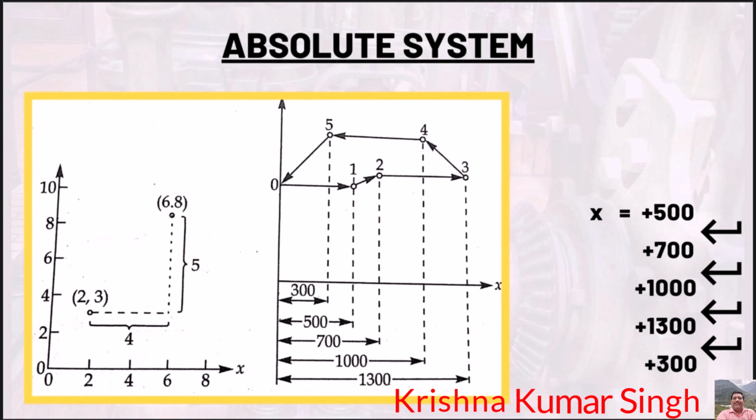Next we have the absolute system. In this system, the movement commands are with reference to the origin. The movement from point A to point B is specified as x = 6 and y = 8.